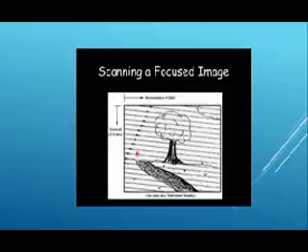Scanning is a technique that divides a rectangular scene into individual lines. The standard TV scene dimensions have an aspect ratio of 4:3. That is, the scene width is 4 units for every 3 units of height. To create a picture, the scene is subdivided into many fine horizontal lines called scan lines. Each line represents a very narrow portion of light variation in the scene.